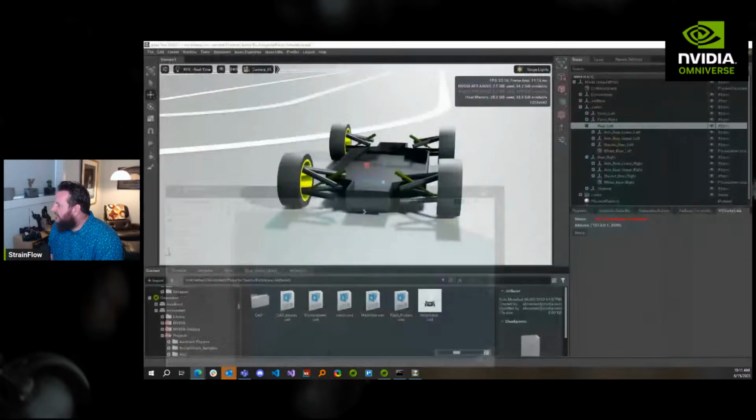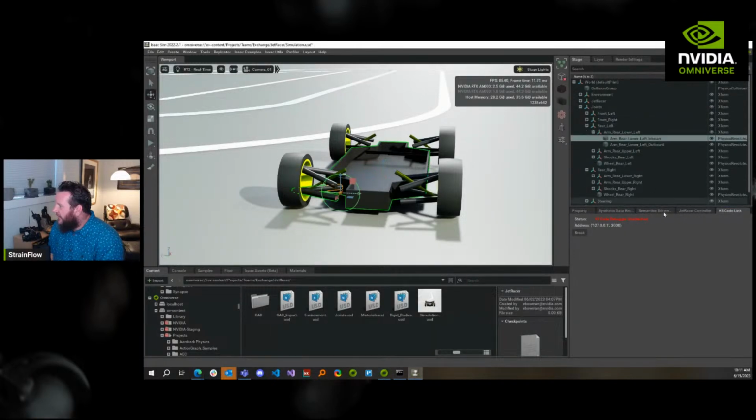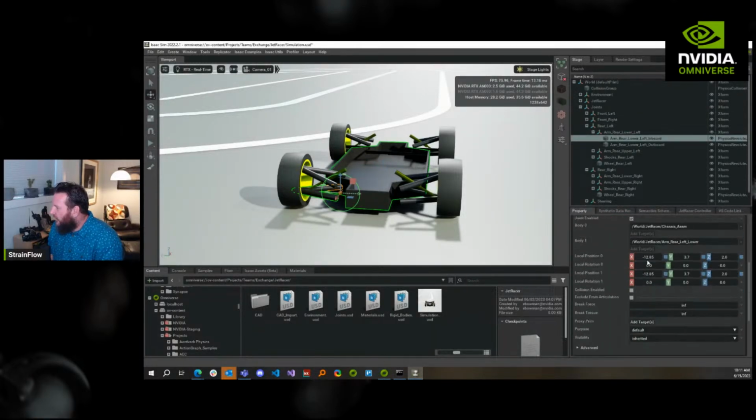So if you look at a joint and it says, okay, what are the two parts, and then what's the position of the joint relative to the origin of that part? Well, you have to figure that out, unless you do what we've done with Onshape and have everything relative to the global origin, which is actually common skeletal modeling in practice within CAD anyway.